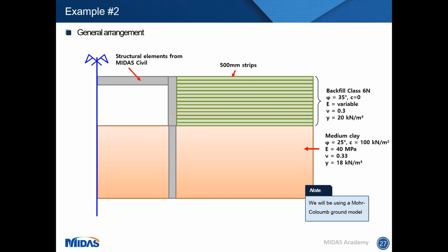Since we are checking now only expansion and contraction, we are going to use symmetry. So we are going to just model half of the ground and half of the bridge. Just with expansion and contraction, you can do that. But for other more complex cases, or when you want to start taking into account, for instance, braking and acceleration or unbalanced loads on one side and another, then you will need to model the whole bridge.